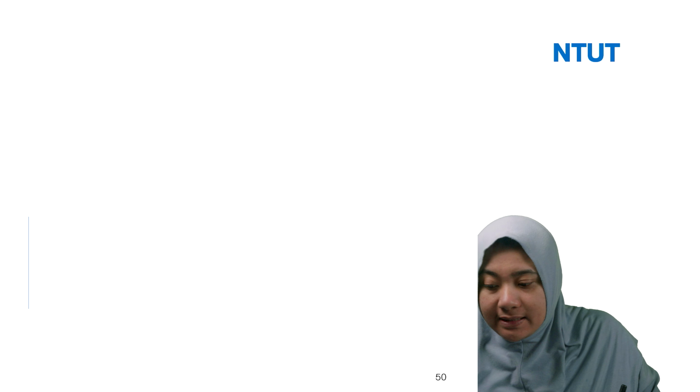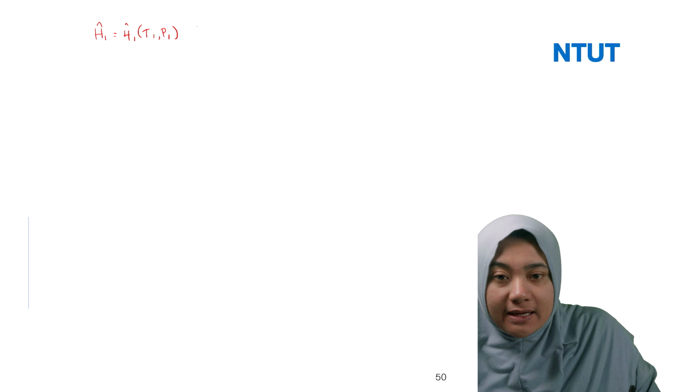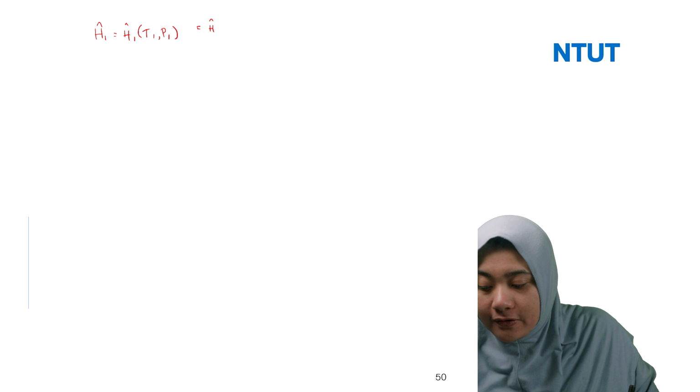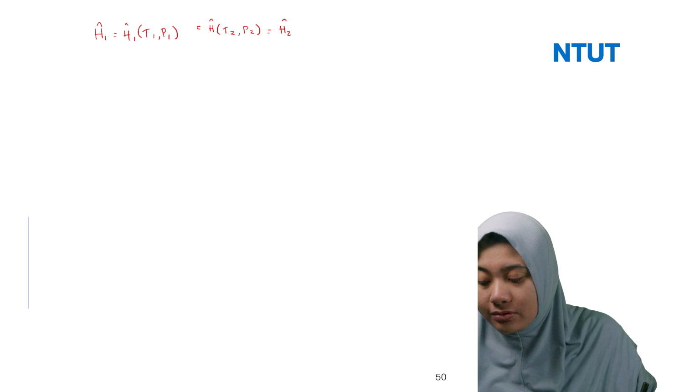Because in this case it is a Joule-Thomson expansion, H1, which is the H at T1, P1, is equal to the H at T2, P2. So it is equal to H2.